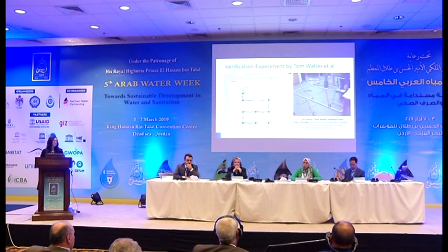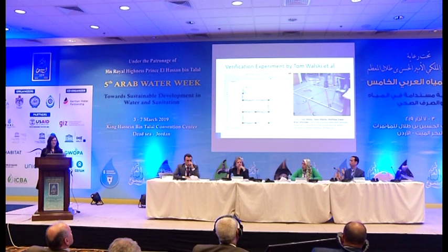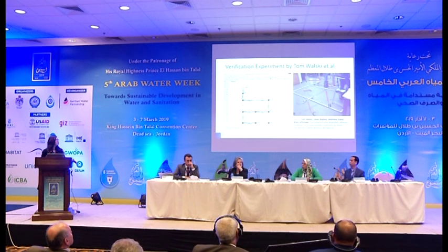Now, the methodology of using pressure-dependent supply through the emitter equation or the orifice equation has been verified in the lab using an experiment, and this experiment was done by Tom Walski. Basically, they simulated the hydraulic model on a physical system. They used a PVC network of 1 inch in diameter, with the tank at the supply node on the top, and they had 2 outlets.